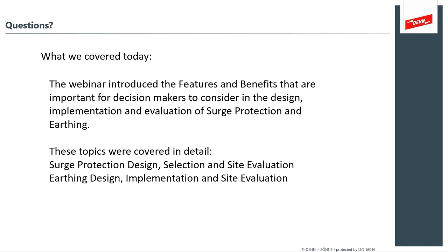Mark, the questions keep on rolling in. Excellent. I'm going to ask you, I just want to find something that is really relevant. As per the questions you mentioned for selecting power SPDs, we need to match the SPD kA rating with the corresponding circuit breaker kA rating, or with the bus short circuit rating.